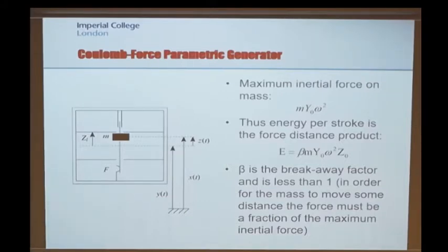That's the type of movement that I'm now going to analyze, because I'm interested in seeing, as I said, can this be better, particularly for scenarios like the Seiko Kinetic watch, where there's no obvious reason for me to use resonance, because I can't make use of the resonant gain anyway, because the device is too small and the movement that's powering the device is too big. So what I did here was to calculate the total amount of energy that you can get per stroke as this device flies from one side to the other.